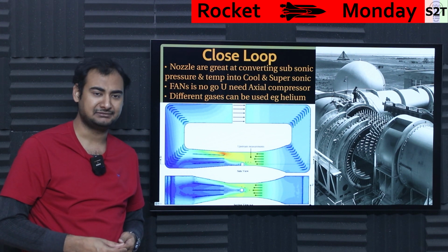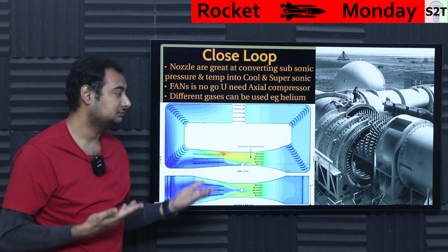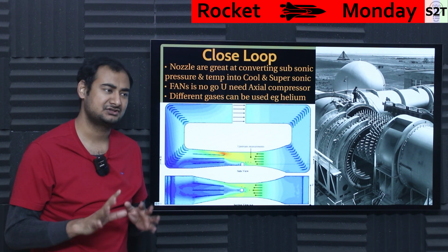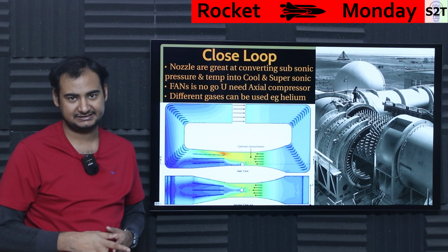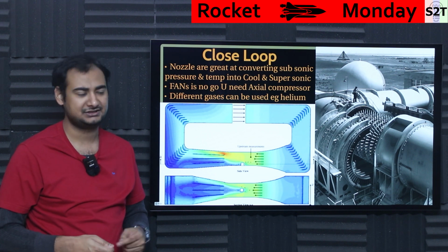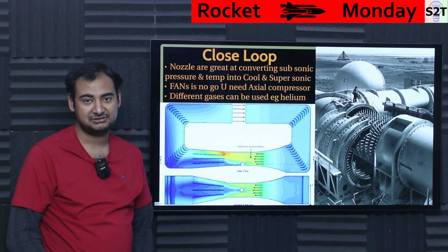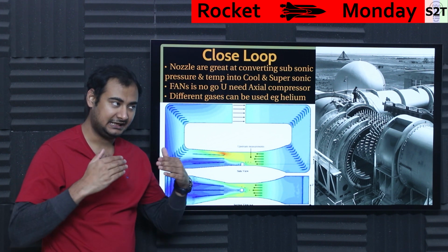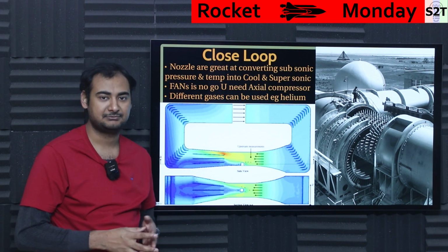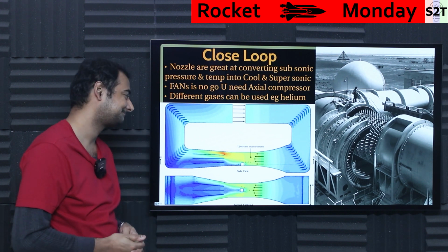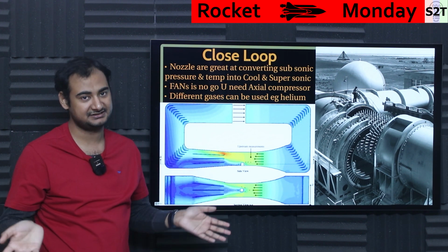For example, helium. You can do that, and people do that in some scenarios where they're like, I really need hyper high speed, meaning if you want to cross, generally it's said, Mach 4 to 6 or 8 regime, you may need to change air to helium or argon depending on your requirement. Generally people change it. Now, is that absolutely accurate recreation of what's going to happen at high altitudes? No. Is it useful? Yes. So people do it. Because again, shock geometry is the same.